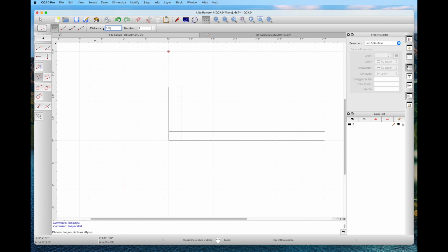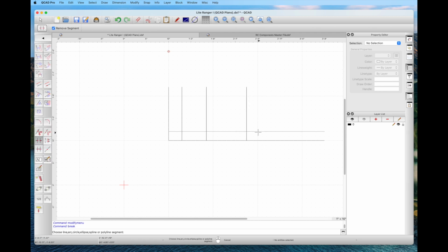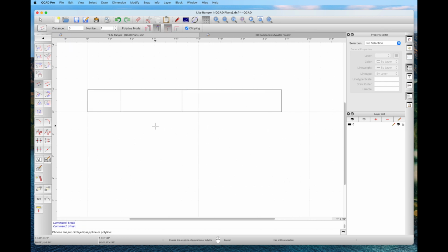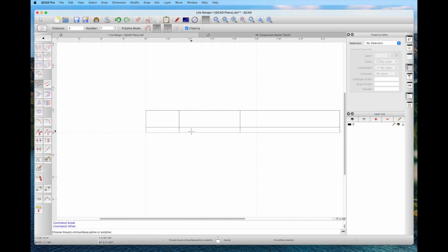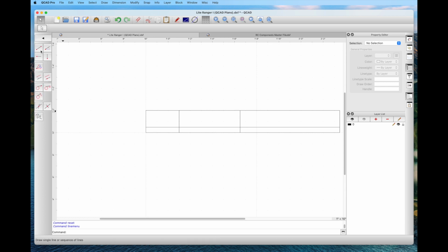Again, this is a 3-inch distance. That'll be the leading edge of the wing. And 5.5 is the wingspan itself, and then 9 inches will be the rear of the airplane. Now I can use the breakout segment tool to trim that up, and we have a little bit neater drawing that we then use to complete the fuselage. This will make sense as you see things go in. Now another line goes up 1 inch from the bottom, and I can draw a line from the intersection to the nose. That's the lower part of the nose gear. Right click to get rid of that.